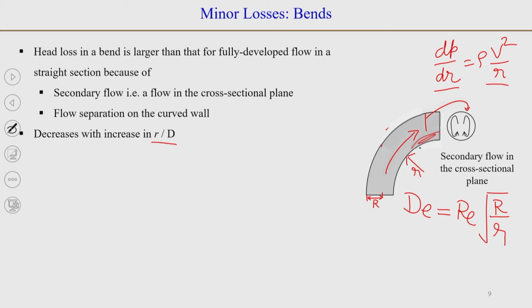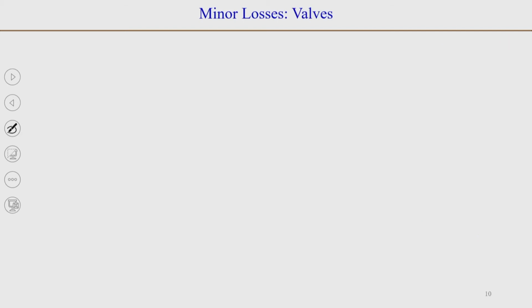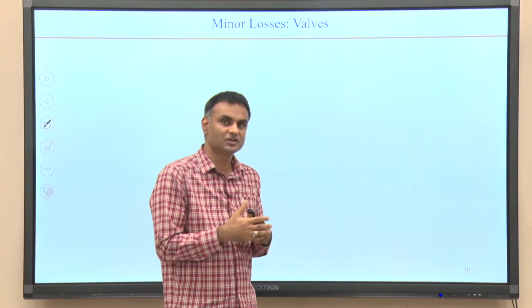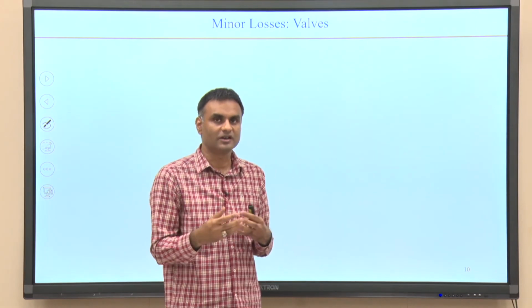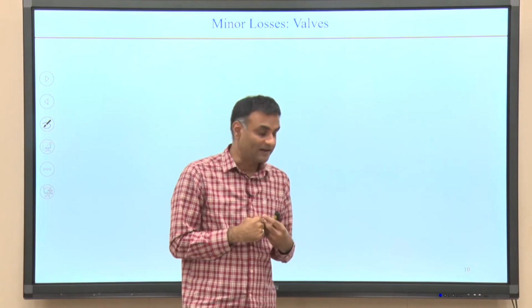And the same is true for the flow separation, because the turn happens smoothly. Okay. So, the R value you can see from here, the strength of the centrifugal force will decrease if R is large. Okay. So, you can look at the values in manufacturers' data or in the handbook for bends.